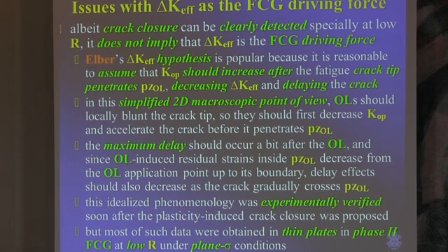In my point of view, it has a huge problem. As a mechanical designer, I do not know how to calculate the opening loads for all specimen or component geometries. I can calculate the stress intensity factor, but I cannot calculate the opening loads. So from my point of view, the use of delta K effective as a mechanical designer is a major problem, because I have to assume some simplifications in order to calculate the opening load.